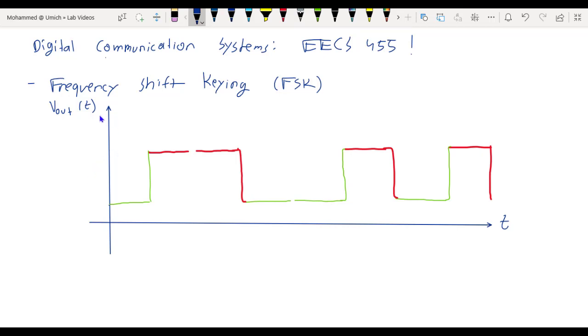So for instance, if this was the output of the envelope detector when I input the audio file into my frequency discriminator circuit, then I would write down 0 for the first tone, 1 for the second tone, 1 for the third tone, 0 for the fourth tone, 0 for the fifth tone, 1 for the sixth tone, 0 for the seventh tone, and 1 for the eighth tone. And then from that, you can convert this 8-bit binary string to base 10 and obtain the actual message.